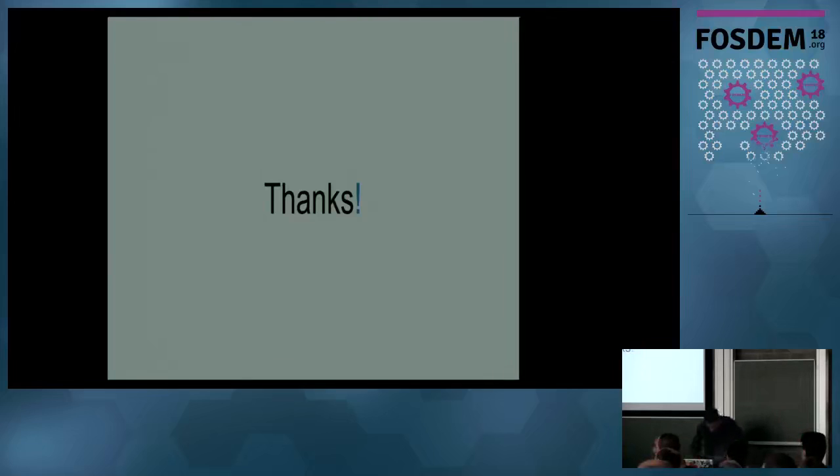Is that just strictly an HTML or just a text file? The files are plain JSON files with some kind of structure to represent all the diagrams and the connections. And then I have a compiler from this JSON to Verilog that is inside the Icestudio. So now the format is JSON.